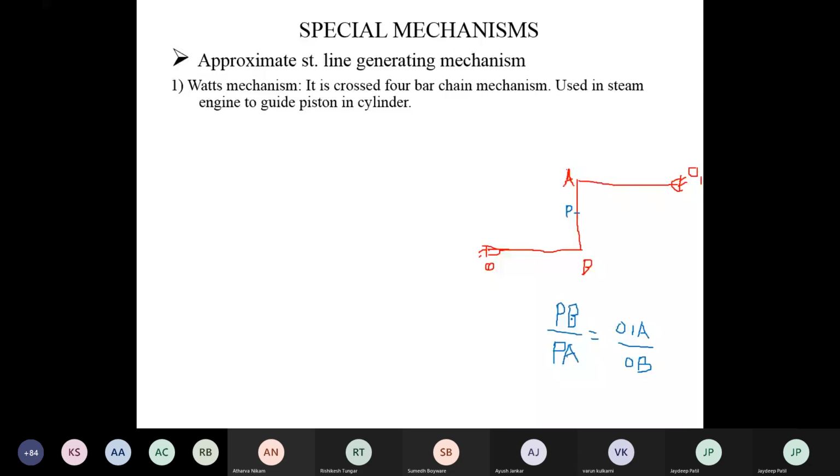This is the initial position of the mechanism. At this position, consider the ICR of link AB. ICR means the instantaneous center of rotation, the center about which link AB turns. How do you find it? Draw a perpendicular through B and a perpendicular through A; where these two intersect, you get the center of rotation of AB. From the figure, the perpendicular lines through B and A never meet, as the intersection is at infinity. So at the initial position there is no ICR of that link. Now we displace the mechanism.